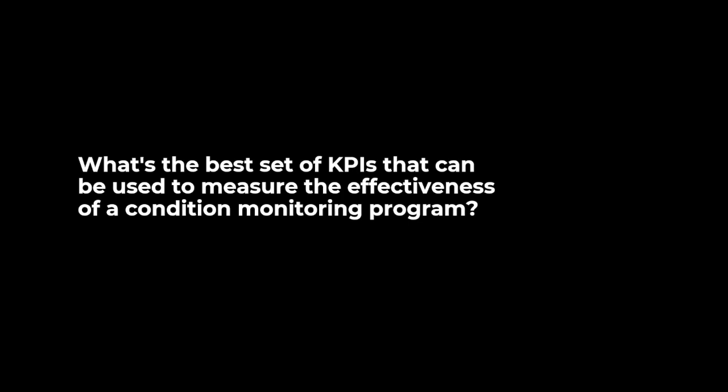The first one is MTBF, which is your mean time between failures. This measures the average time between any two failures, and it evaluates the ability of a program to detect these failures and prevent them. The second thing we commonly use is mean time to repair. MTTR measures the average time it takes to repair equipment after a failure has occurred.